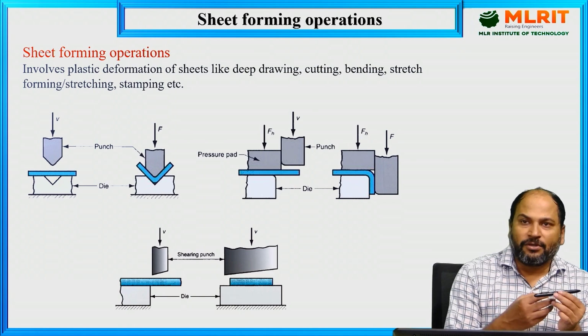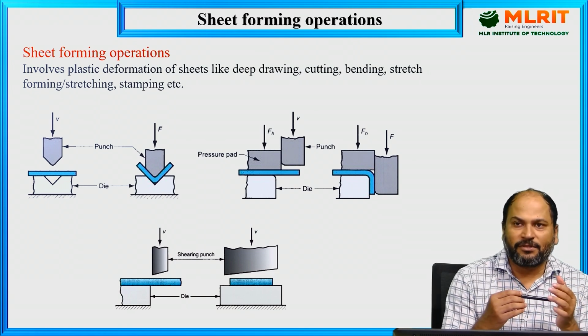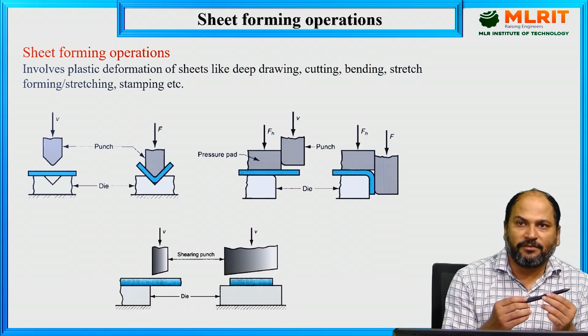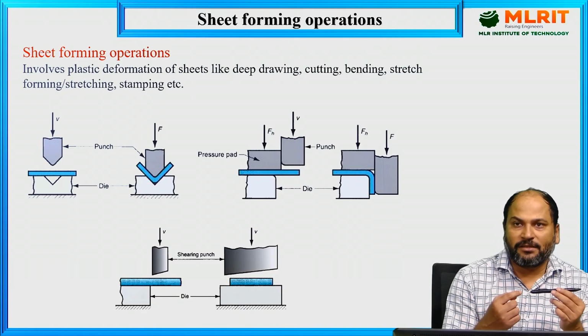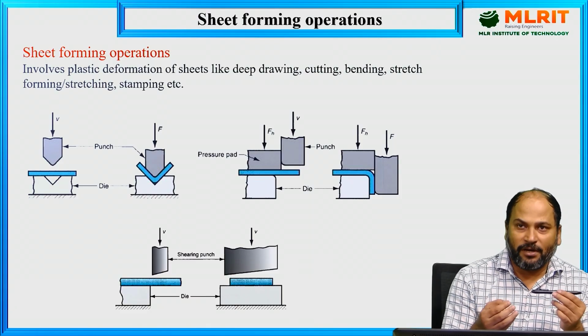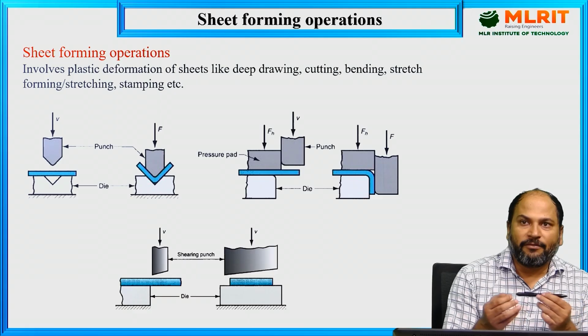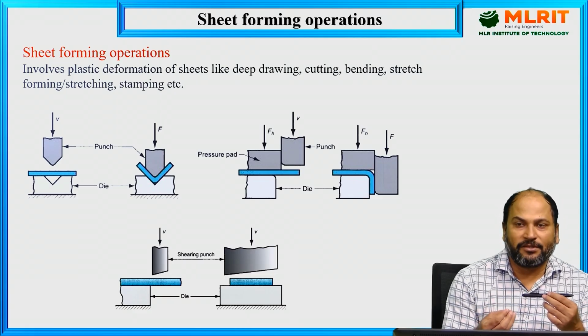Similarly, if I have to increase the cross-sectional area, then of course I will have to apply compressive forces from both sides. Its length will decrease but its area of cross section will increase. So what we are doing in metal forming, as already discussed, is only applying forces, maybe one force or a combination of two or more forces, to change the shape and size.